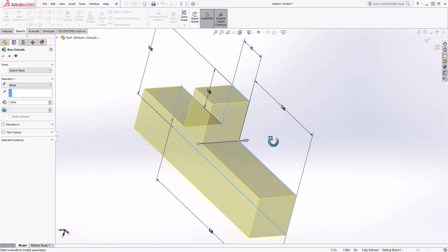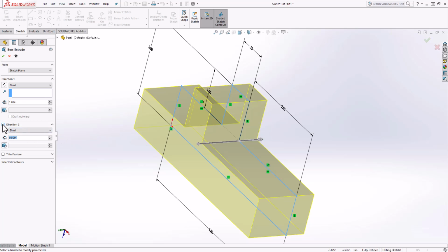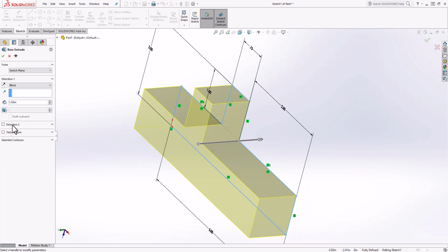And so you're seeing, I pulled it out with the little arrow. You can also push in, like those are options. If I only want to go one direction, I'm just going to turn that option off, and I'm going to set this to 1 inch, just so my dimensions are all locked down.